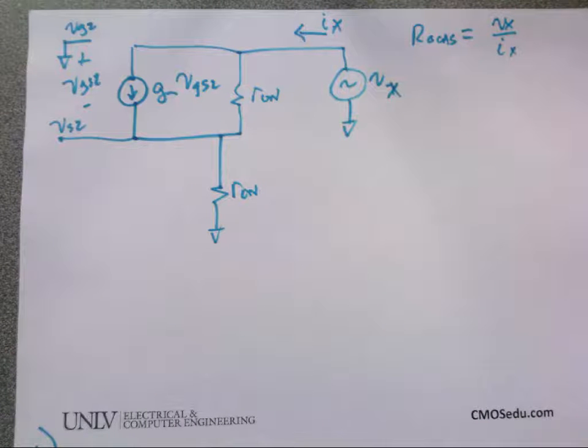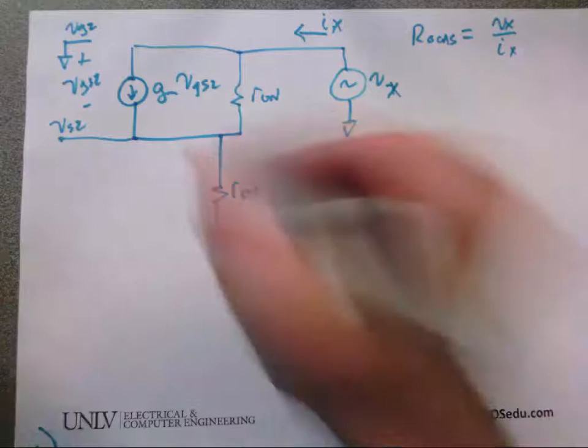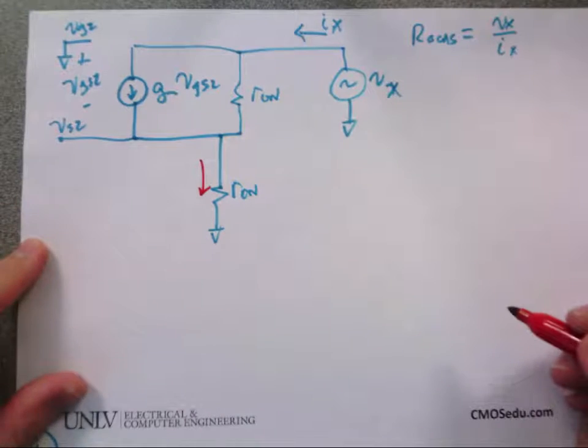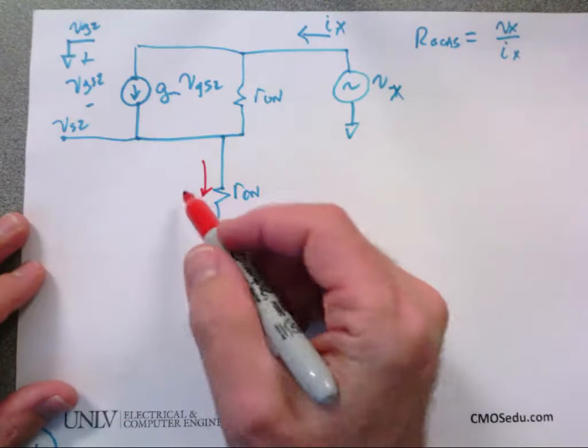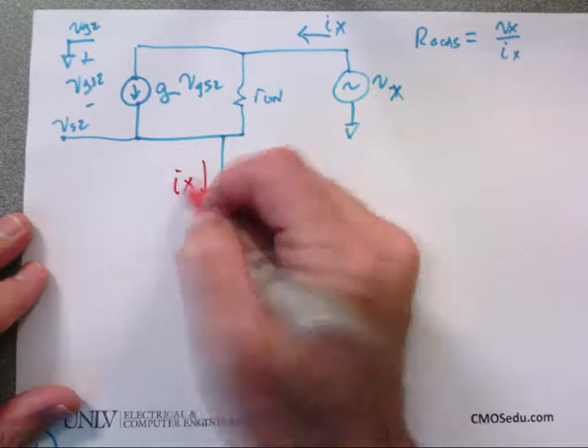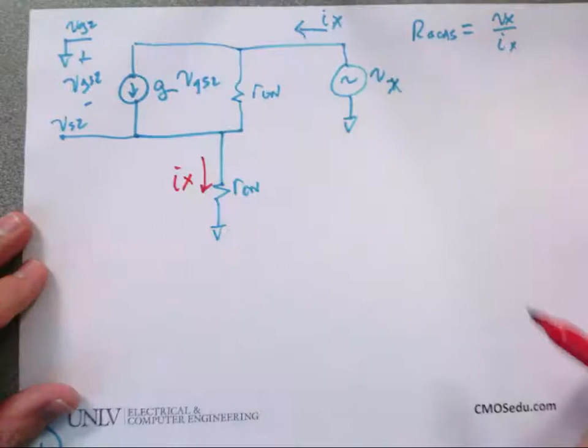R out of the cascode, that's the impedance of the main. Yeah, that's the flat area there. Right, but then the voltage between the 2 resistors is Ix times R. All right, you're getting ahead of me, but let's write that down. So the current, that's one of the tricks. So I already removed this bottom current. This current's what? What flows in has to flow out.